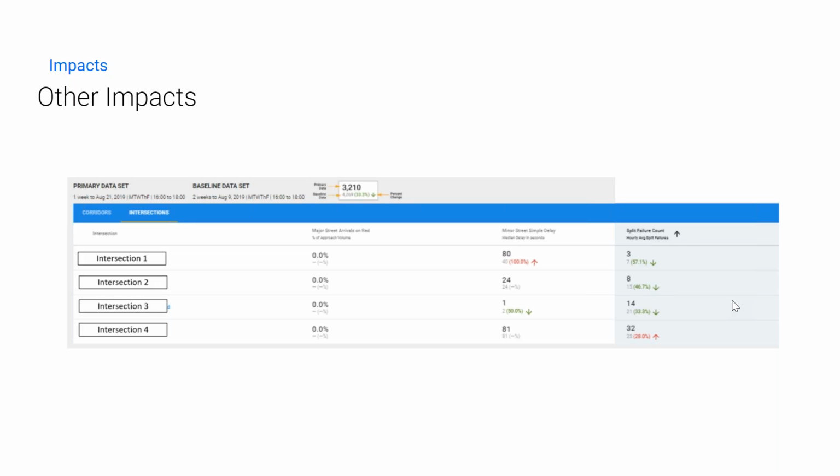So it's benefiting everyone. At one of the intersections, there's an increase in split failures, but that's understandable because one of the intersections, if you remember, was operating on a 170-second natural cycle length, but we needed to bring that down to 140 to be able to coordinate. There's an increase there, but that's understandable. There's video there, and I actually checked the video. There are split failures, but they aren't massive queues that are remaining. It's 1 or 2 vehicles. So with a simple split reallocation, that could probably be addressed further.